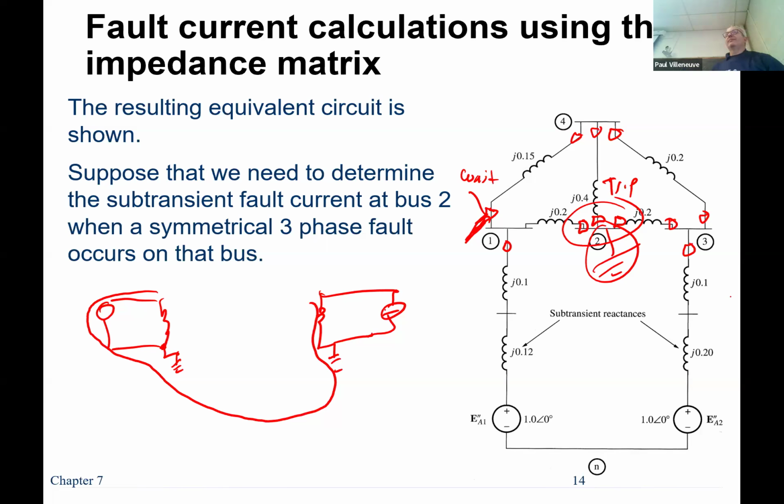So why didn't they survive? Because the load was so light, it wasn't enough to get the differential element to operate. It was at that point unloaded or very lightly loaded, because they did a bump test on a 1,000 horsepower motor, and that pulled 60% of the transformer's capacity, because when you bump it, it pulls a lot of power. But it was able to stay in.